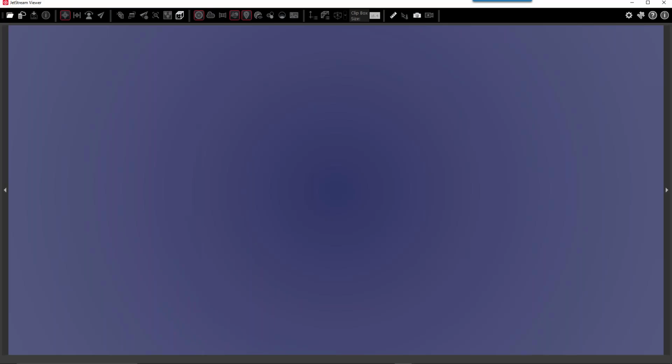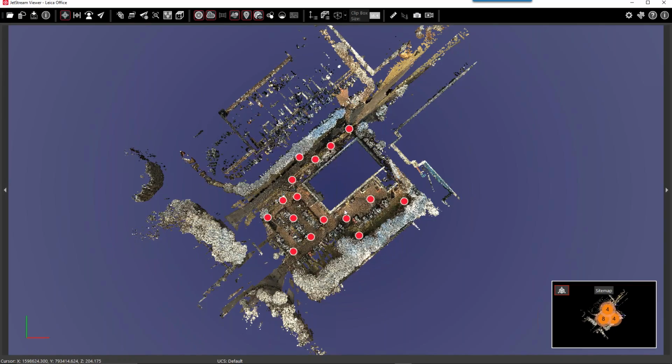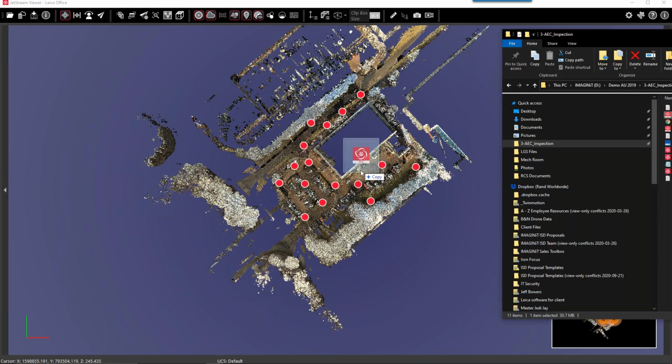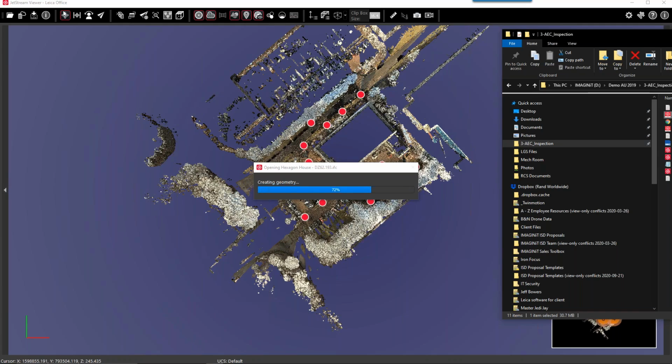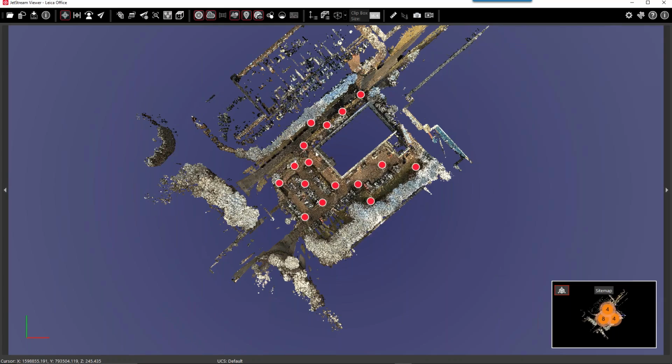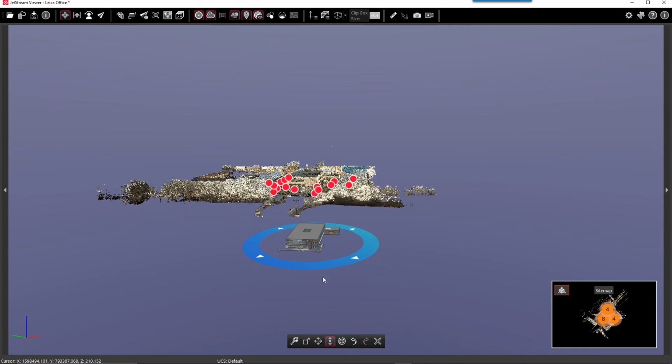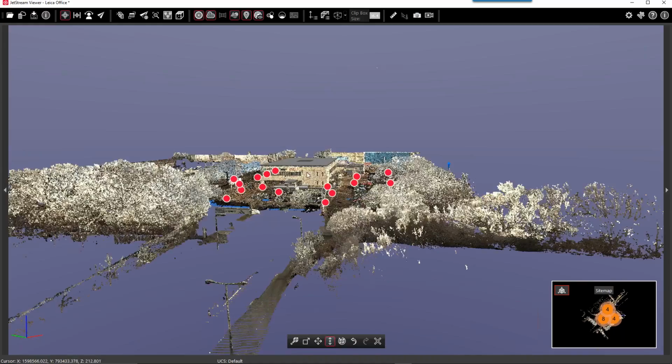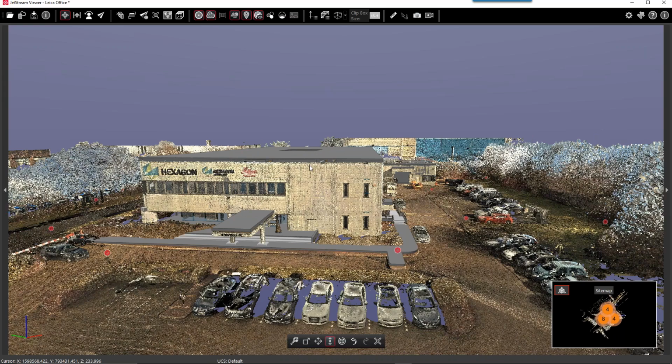So Jay, you mentioned with that point cloud, using it in different applications and creating a model from it. And I know we can't show everything as part of the workflow in this presentation, but can you explain what the process would be of taking this point cloud into a modeling authoring program like Revit and maybe making it a parametric model, as opposed to right now, really what we're getting from the point cloud is a really great, accurate measuring tool, right? Right. And to take it into something like Revit, there are softwares out there, for instance, CloudWorks for Revit, that allow me to bring the point cloud in and then use my point cloud to be able to create walls, doors, windows, piping, structural steel.